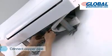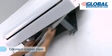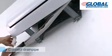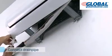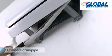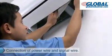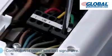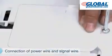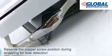Connect the copper pipe. Note that the copper pipe should be free of bending and deformation. Adjust the drain pipe of the indoor unit according to the reserved length of the drain pipe. Note that the interface should be sealed with adhesive tape. Connection of power wire and signal wire. Wrapping is conducted in order, where the power wire and signal wire are at the upper side. The connecting pipe is in the middle and the water pipe is at the lower side. Reserve the copper screw position during wrapping for leak detection.